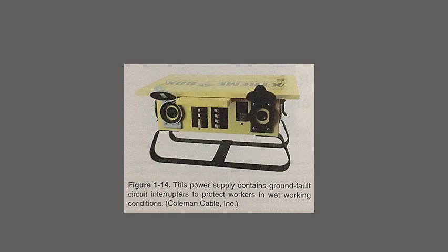Fumes. This may not seem to be a concern for electrical workers, but flammable fumes affect everybody on the work site. Always avoid allowing flammable fumes near any electrical equipment. A simple light switch can create a spark large enough to ignite the fumes. Non-flammable fumes, although not a fire hazard, can be just as dangerous.